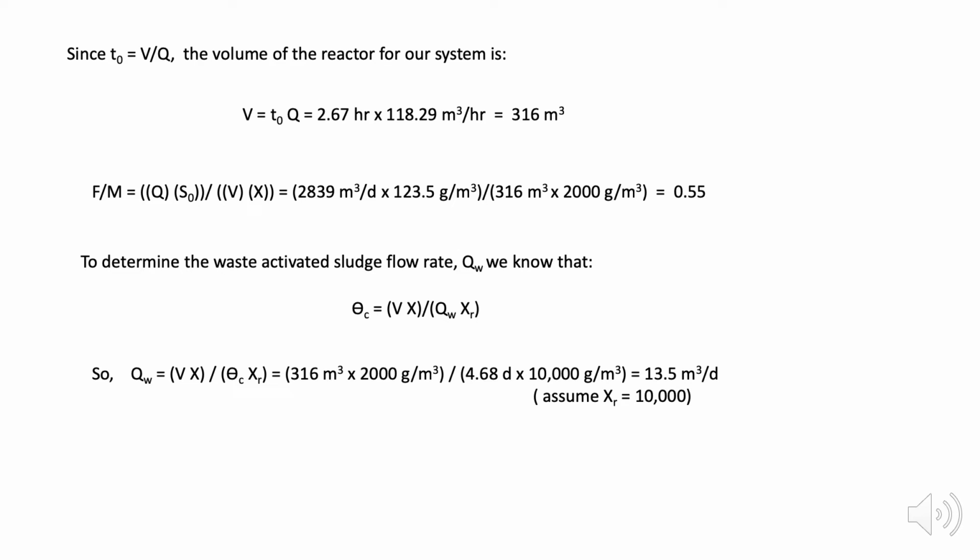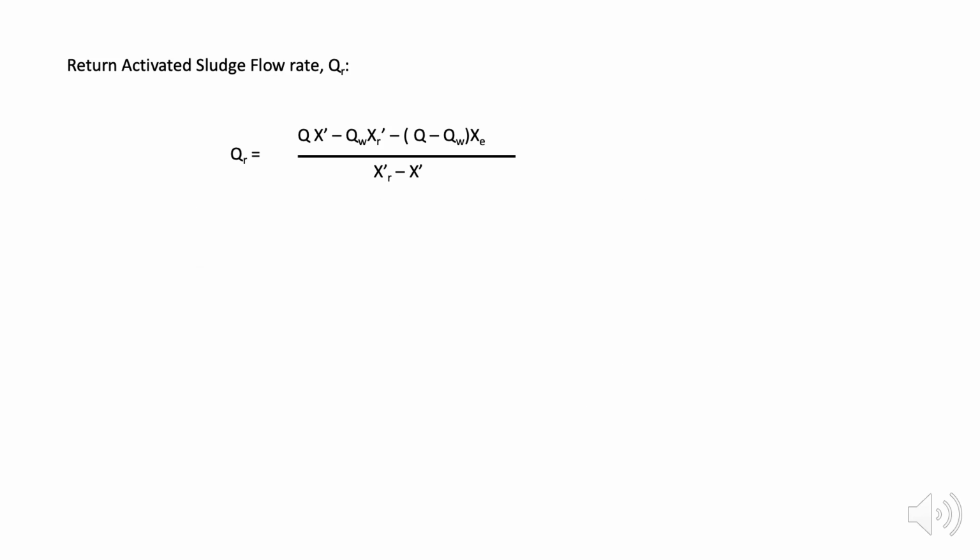So we've got to choose a value that's in a range that's going to work, and typically it has to be greater than X. And the greatest it can possibly be is probably about 11 or 12,000. So 10,000 is on the high end, but I've chosen 10,000 here. Then we just have to recognize we designed the clarifier so that I can get 10,000.